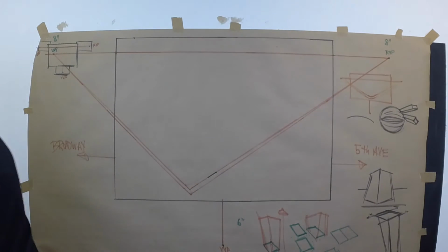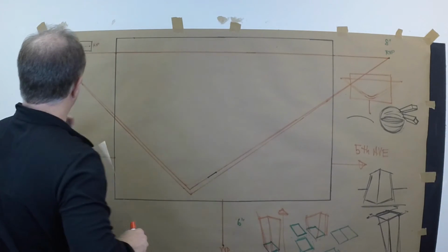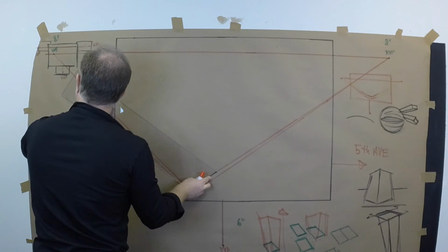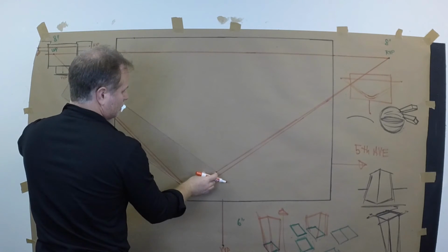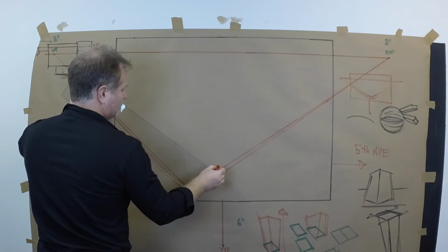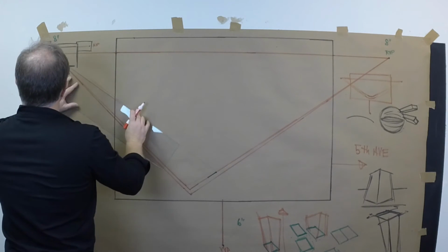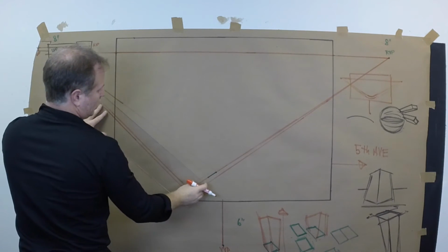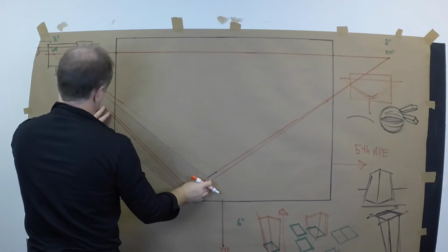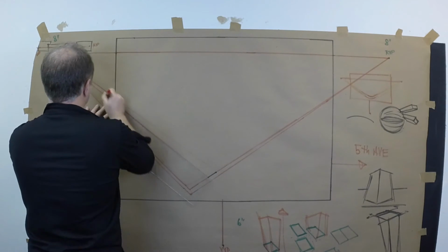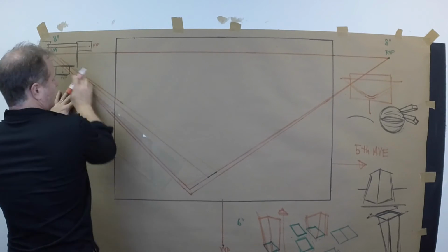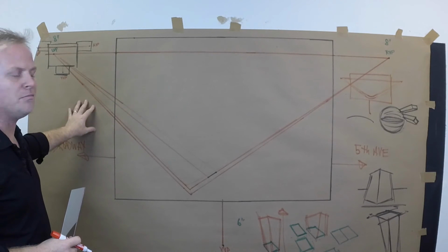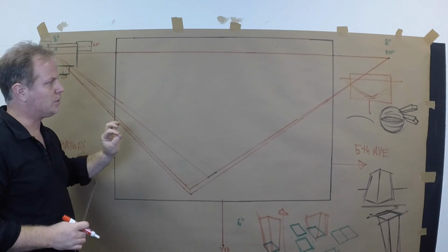And now we need a projection for depth. So we'll go back to the left vanishing point. Here I need a little longer ruler. I think that'll do it. So all the way back to the left vanishing point here, and here as well. All the way back there. There we go. Okay. So you're going to have a lot of convergence lines. Just be mindful. You have to draw very light, very technical, and very tight.